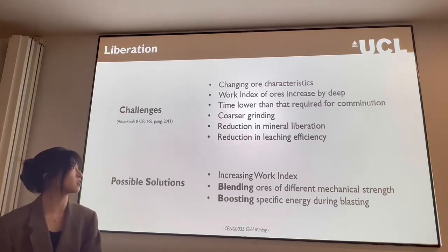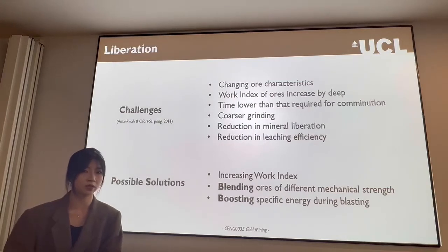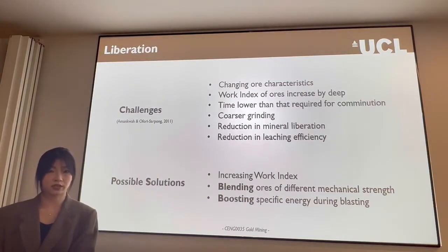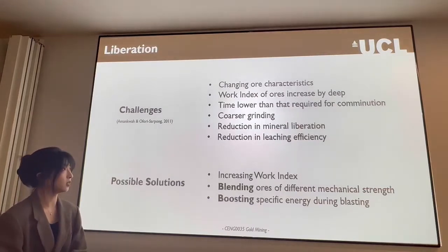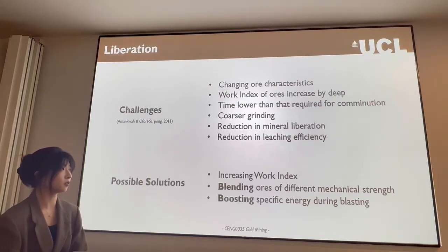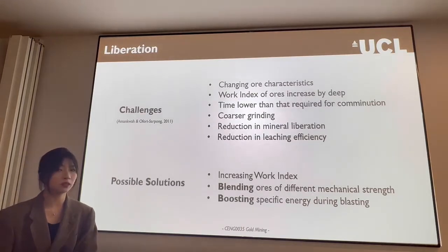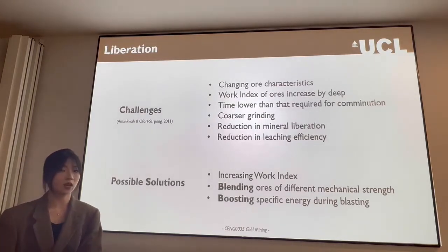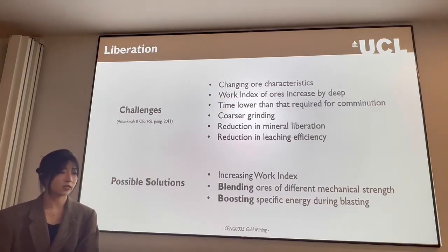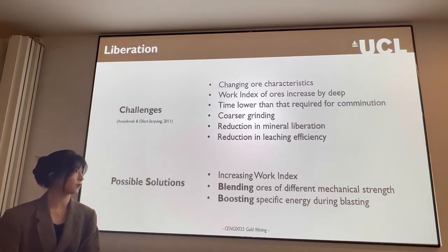One of the reasons is the work index of the ore would be increased by the depth, and also it shows that the installed energy would be reduced by the depth, and the time required for the comminution would be lower than the required targets. So that's one of the reasons for the cross grinding, and also that will lead to the reduction in the mineral liberation with the reduction in leaching efficiency.